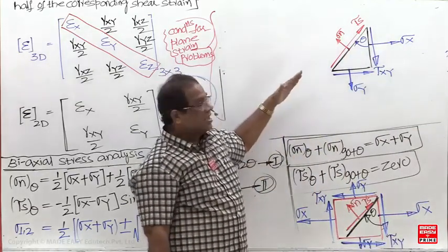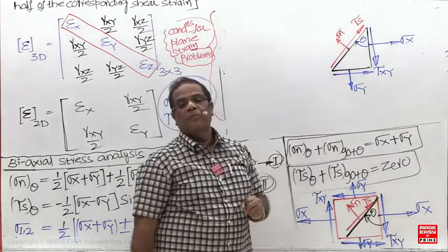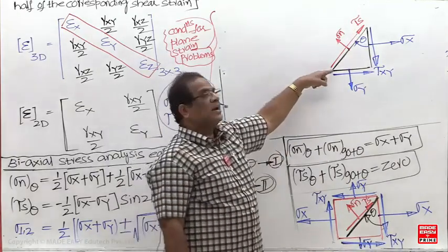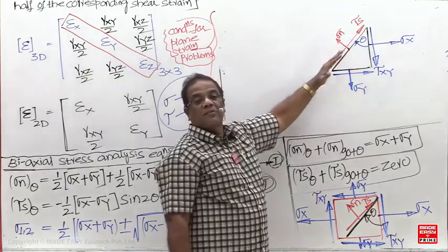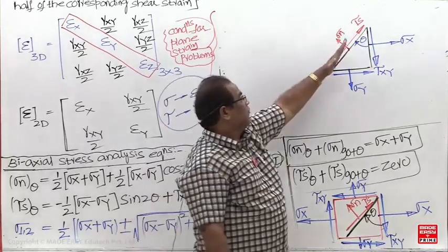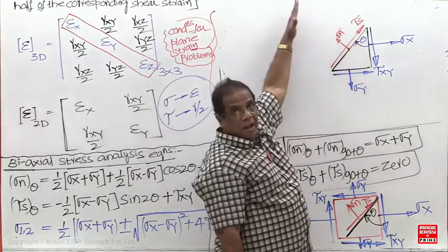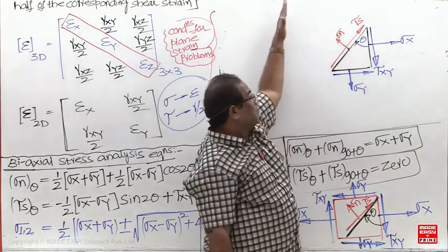So while deriving the equation, I don't know this direction. I have assumed this is upward. Now is this clockwise or anti-clockwise? How to decide this? Yesterday I studied that always on two parallel planes the shear stresses are equal and opposite in direction. For this one, where you are going to get a parallel plane above, draw the remaining part of the square.